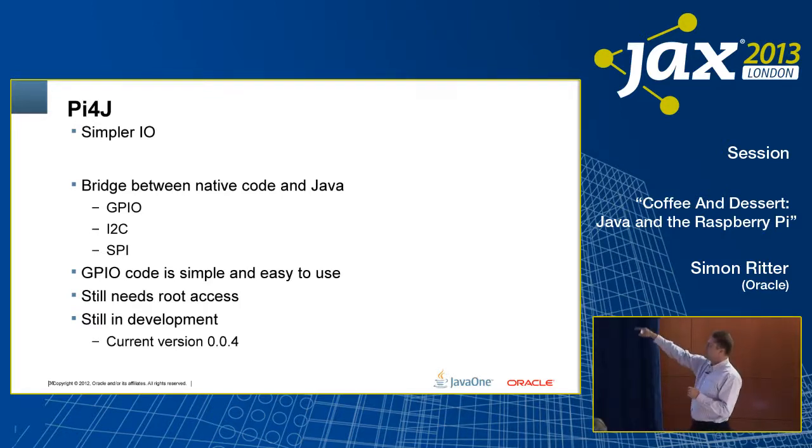And again, there's a nice simple chip that you can get. Doing electronics nowadays is actually quite simple. Don't even need any other external components. If you get the right version of this, you get the L293D, because that has all the diodes internally, otherwise you have to put them externally.